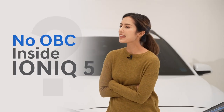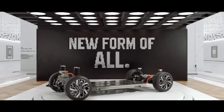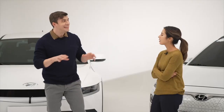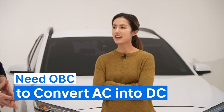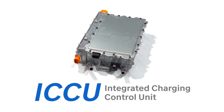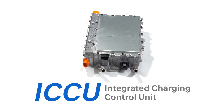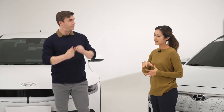Well, didn't you say that the Ioniq 5 doesn't have an OBC? No, that's not right. Even the Ioniq 5, which uses the E-GMP, still has an OBC. It needs the OBC, if you remember, to convert the AC into DC. That's right, yeah. However, starting with the Ioniq 5, the OBC has been integrated into the Integrated Charging Control Unit, what we call ICCU for short. So, to summarize, AC from charging is converted into DC by the OBC inside the ICCU. All right, I think I got it. Good.